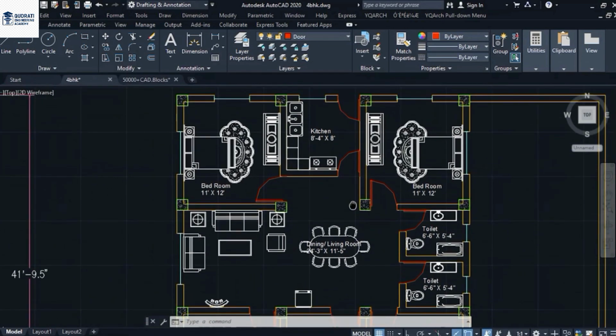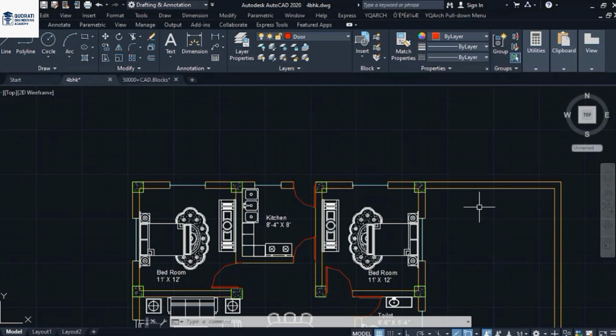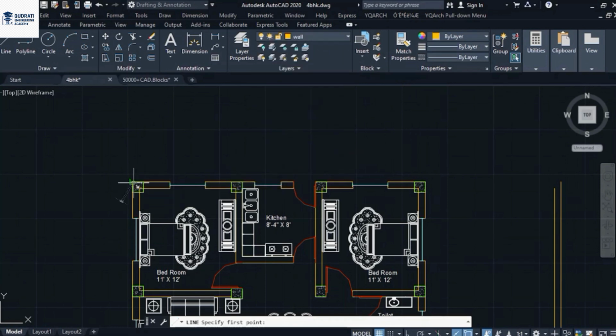So as you can see here, kitchen, there is a door behind the kitchen for going to the garden, or you can say yard. So here we will make the fence a little bit bigger because there is a door behind the kitchen. So there should be an area for that. So I'll choose auto mode on, and then 8 feet is enough.